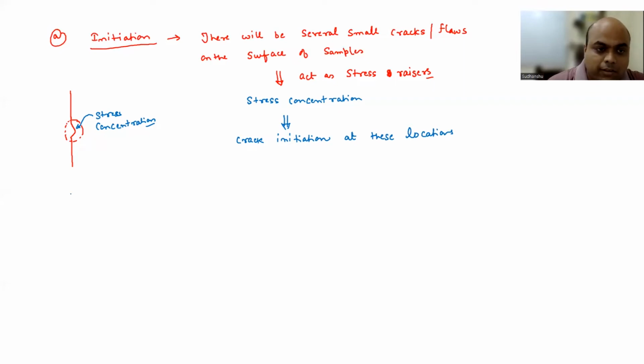Okay. So remember that, even if your material or your sample is under elastic loading, these stress raisers can enhance the stress in front of this defect to such a great extent that the crack can initiate, even though your applied stress is below the yield point. And that is why I mentioned, when I started talking about this topic of fatigue failure, that it is very dangerous, because fatigue failure can occur even if the applied stress is below the yield point. Okay.